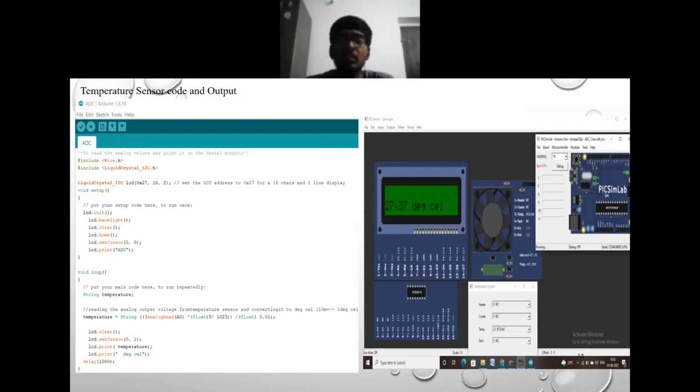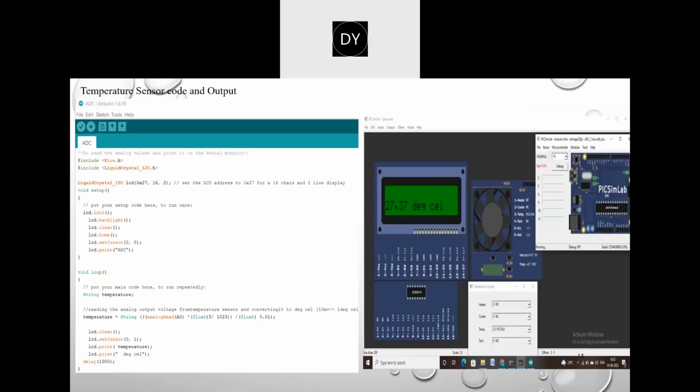And we are taking the next concept as a temperature sensor. We are displaying temperature in degree Celsius. Firstly we need to take the components CLCD and temperature sensor from the inputs and outputs, and we need to give certain properties with respect to the analog pins in order to print the temperature value on the LCD. And we need to give LCD.print as temperature, and in LCD.print we need to add degree Celsius to obtain the value in Celsius. Next one.